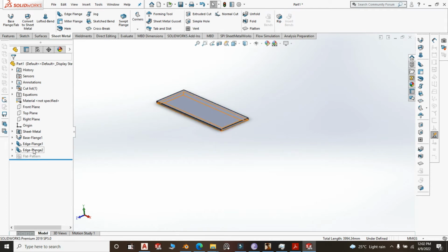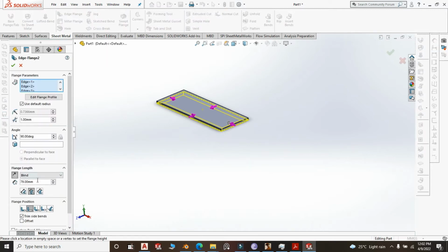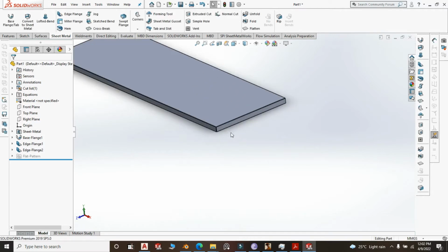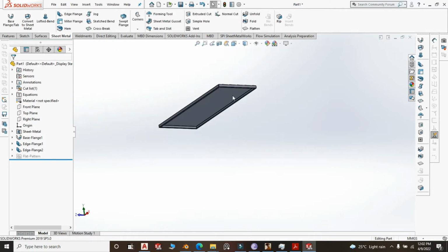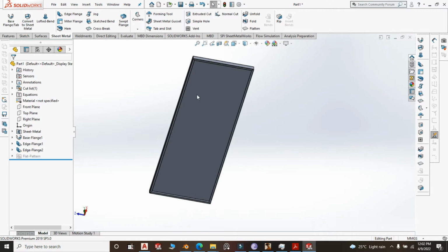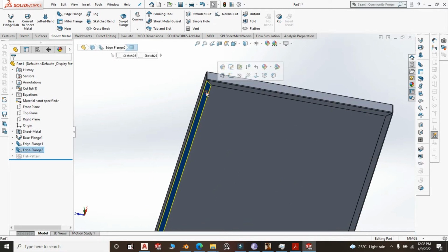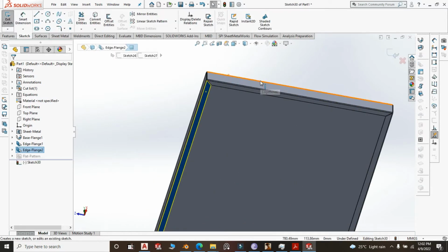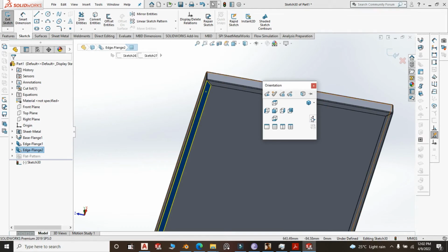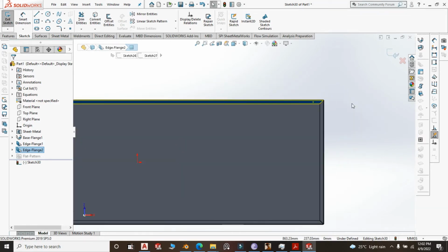We are again trying to minimize waste of material. Sorry, I didn't change this bend to 15 millimeter. Click OK. Then once that is done, this is the top shelf. Once that is done, you come to this bend, start new sketch, hit shift, go into normal,